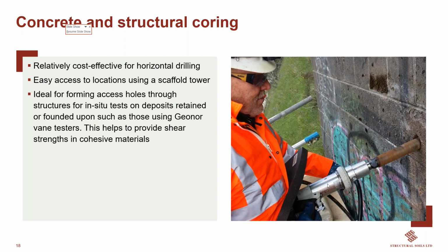So there are 2 different types of concrete coring. There's hydraulic, which is this one, and there's also electric. What we obviously don't want to do is use the electric one when there's water around. So hydraulic is the most versatile.